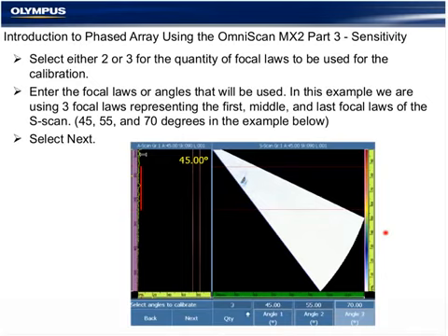It's strictly amplitude. But in the wedge delay, every angle is going to hit the side drilled hole a little differently, and it is relative to the position. It's another reason we use radius instead of side drilled hole as the preferred method.